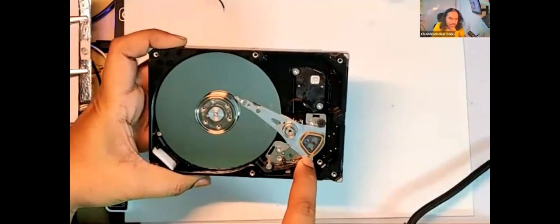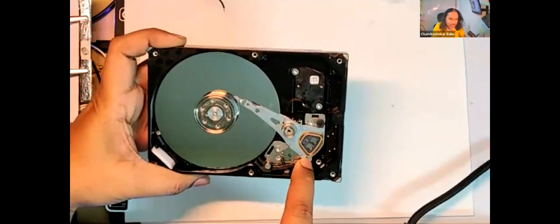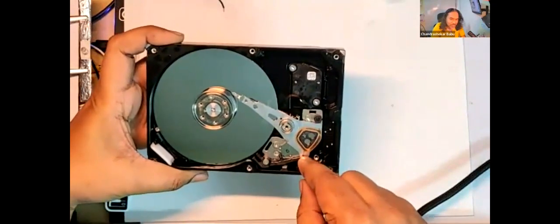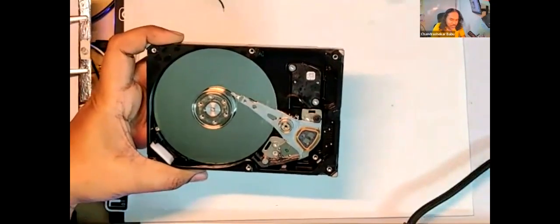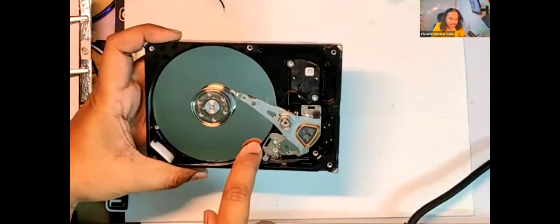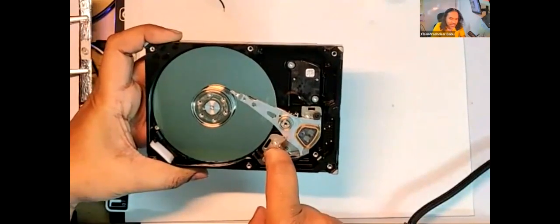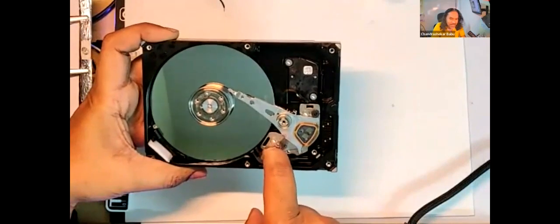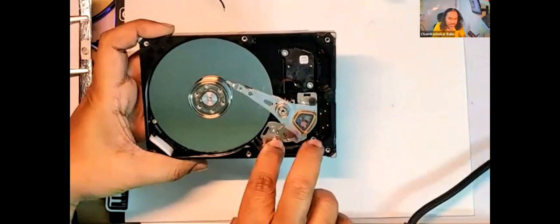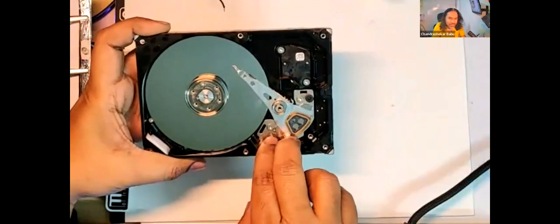This head is right now in what we call a park position, which means when you're moving the hard drive, you don't want the head to just wiggle around and scratch the surface. So they keep it in park position. The moment you power up your hard drive, there's a small actuator arm that moves around here. See this? There's a small magnet, which gets repelled when you apply current to a coil below it, and it just moves, making this head move freely.